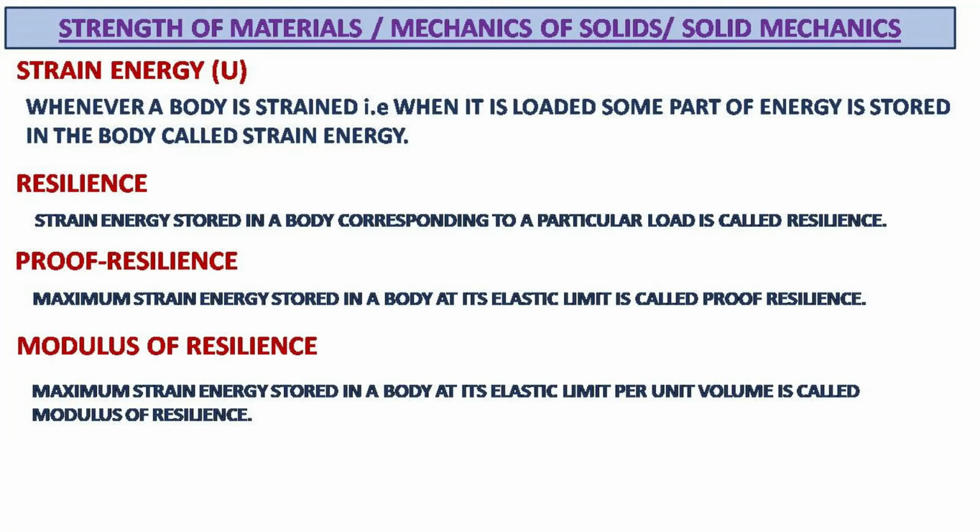Whenever a body is loaded and the load is removed, some part of the energy is stored within the body. This energy is called strain energy. This strain energy depends on the magnitude of load applied on the body. There are some different terms which are used to define strain energy precisely, such as resilience, proof resilience, and modulus of resilience.